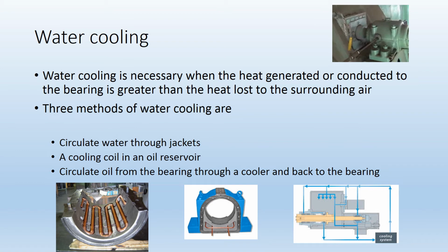When a bearing is generating heat, that heat has to be conducted away from the bearing or overheating will occur. So if the amount of heat being generated by the bearing is greater than the amount of heat being lost to the surrounding air, you may want to water cool the bearing.